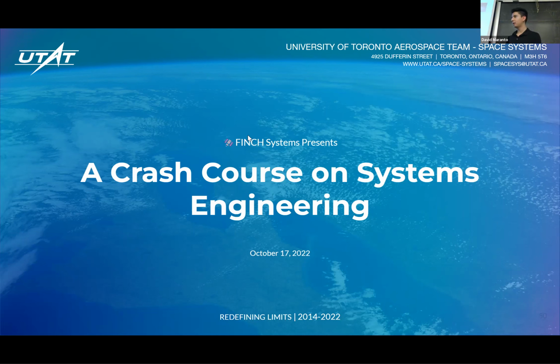In the case of Maggie's payload, we have a very specific vibration testing that we have to pass. Launching on a rocket, you can't have the satellite breaking apart. So we have to design for vibration. How much? We have this number from launch. Let's test to that, and we'll write a requirement that the payload must satisfy this vibrational profile.